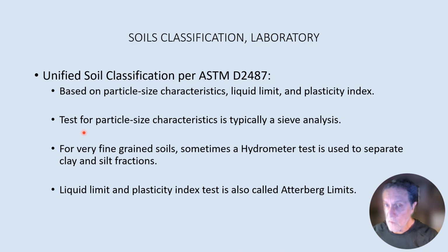Generally speaking, a soil will have many different size particles in it. It's pretty rare when you get a soil that's got a uniform size to its grains. An example of that type of soil might be a very well sorted, poorly graded sand on a beach that's formed primarily of quartz grains, which can be more or less the same size.